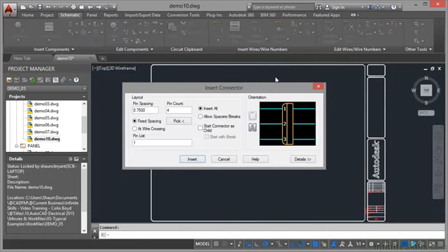Now, connectors are parametric, and again, this parametric linking of blocks and attributes allows you to work effectively in your connector drawing. We've got a pin spacing of 0.75 inches, 3/4 of an inch, 4 pins on the connector, and they're fixed spacing, and the pin list starts at 1. Now that can be changed to something like 0, 1 if you need it to. Nothing to stop you changing that. We're going to insert all of them, and I'm not going to worry about spaces or breaks. I'll show you how all of that works later on in the course.